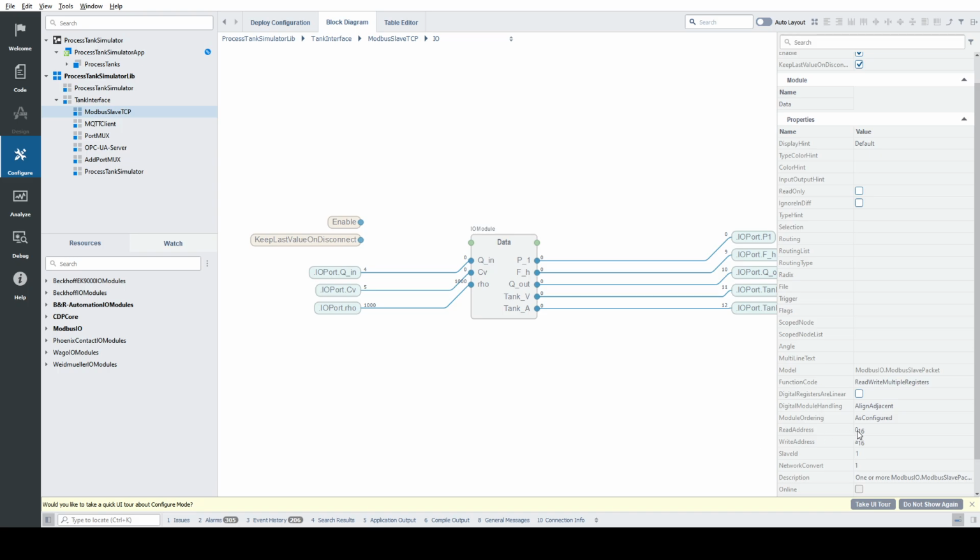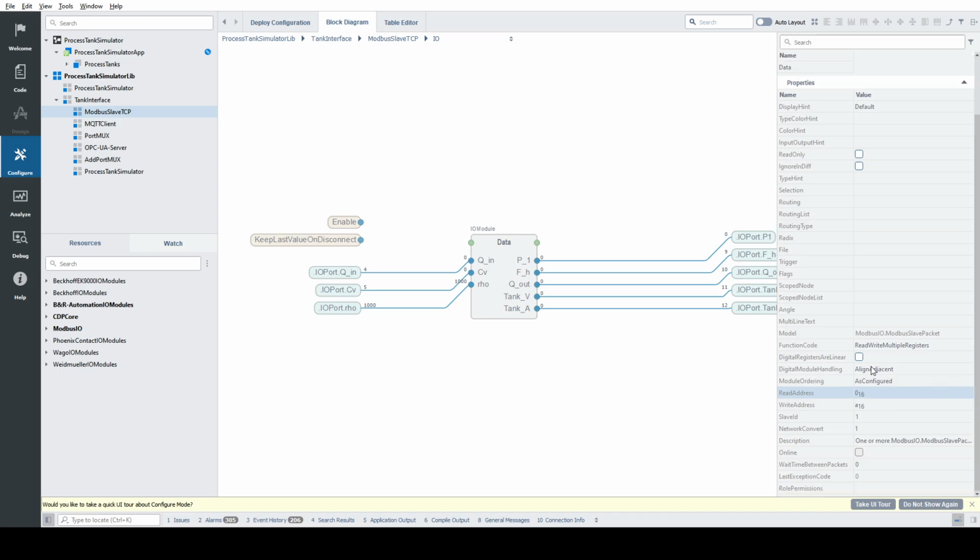And over here, we have also set it so that we have to differentiate it. Otherwise, it will be an error, because the holding registers are 16 bits, and if we set it to the same value, then at the same time Modbus will be reading from it as well as writing to it. So it will be like a clash.